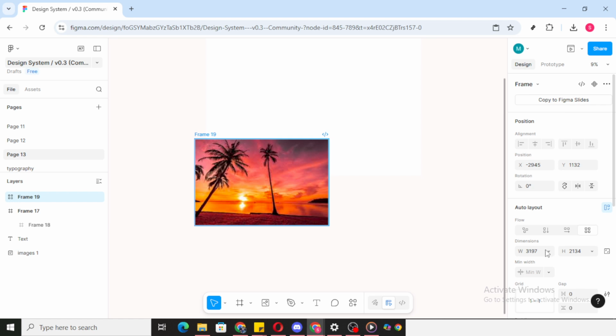And remember, auto layout is non-destructive, so you can adjust, reorder, or remove elements without starting over. That's all you need to get started. Open your project, highlight your elements, apply auto layout with a right click, and use the right side panel to understand and refine what you see. Enjoy practicing and let auto layout do the heavy lifting while you focus on great design.